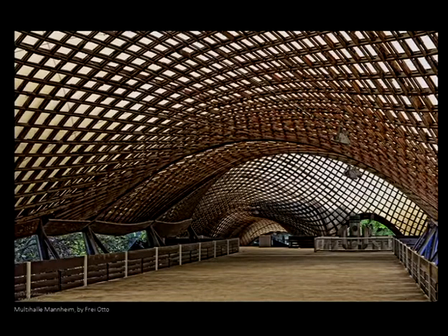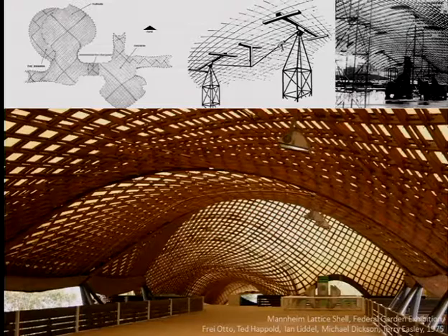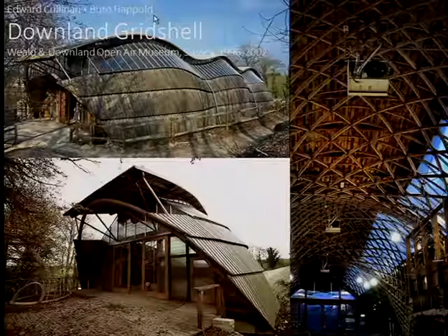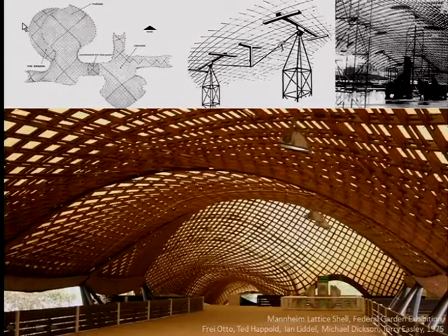This doesn't have to be braced because of the way they do it. First they do the model, form finding. So you see here, there are these very small rings between elements so that they get this funicular shape. Then photographs, surveys, drawings, and then construction. But what they do, they start from a planar grid, and then they bend it, they push it, squeeze it, and lift it up to get the final shape.